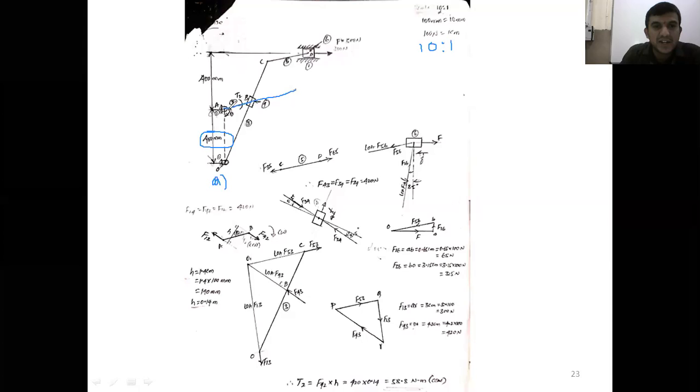Along the 105 degree line, AB, how much AB is there? 200 mm. 200 mm is equal to what? 20 mm reduced scale, or 2 centimeter. Along the 105 degree line, measure 2 centimeter. Through a compass, A is the center, radius is 2 centimeter. Then draw an arc, right? Then you'll get a point B, right?